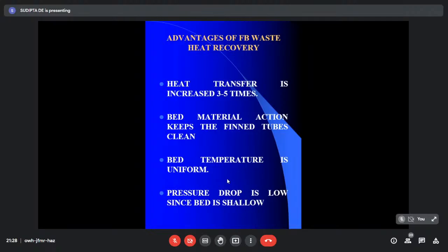But in a reaction process, it's not the same operating zone as the heat transfer zone. Those who are chemical engineering students might know that you need to control the bed height depending on different types of reactions, because reaction in a shallow bed is not very effective; in that case the conversion of the reaction process will be comparatively lower. So there the optimization principle of the bed height is a little bit different from the corresponding heat transfer optimization process.